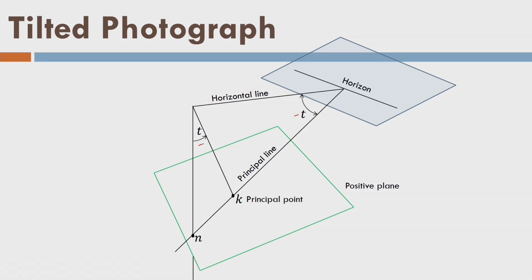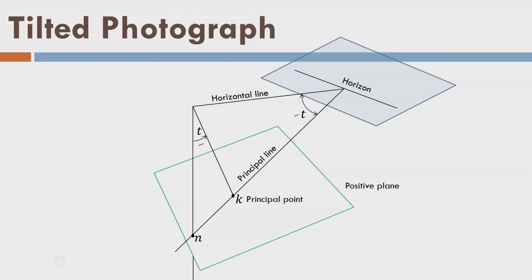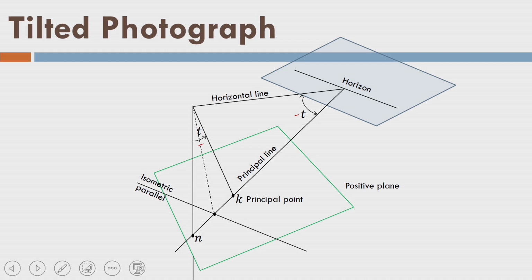They are the same, but they are in different planes, so they appear different in the animation. I am showing that this is the tilt with respect to horizontal, and there I am showing it like this. This is my optical axis by finger and the pen is showing the plumb line. So this is the tilt angle, as shown in the animation. Now if I bisect the tilt angle by a line as shown in the animation, it will intersect at point I, and this point I is called the isocenter of the image. We are trying to find I also, and there is a reason for that, we will see.